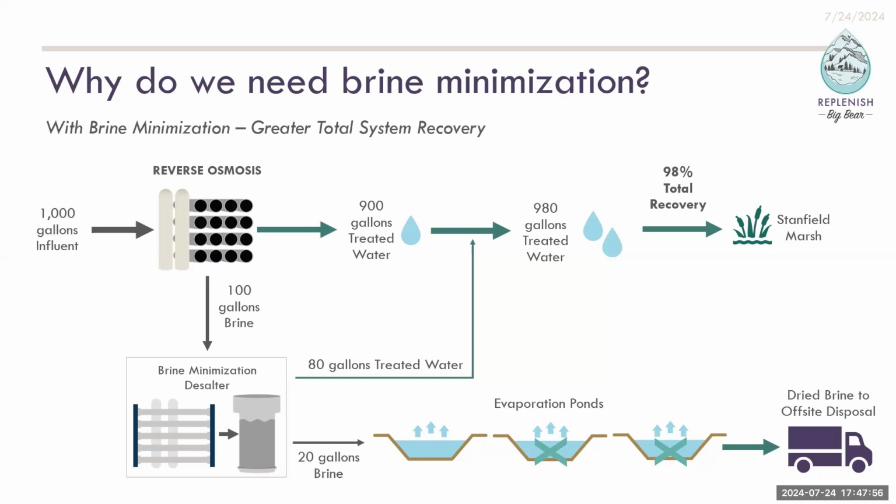Correct, and we use the evaporation data consistent with how Big Bear Lake calculates their evaporation, but we've also got an evaporation pan on site here to get site-specific data as well, which will help us further improve the accuracy of our estimates for the acreage that we need. And of course, we have a safety factor for that as well, to make sure we've got adequate space for really wet winters and redundancy if we need to take a pond offline.